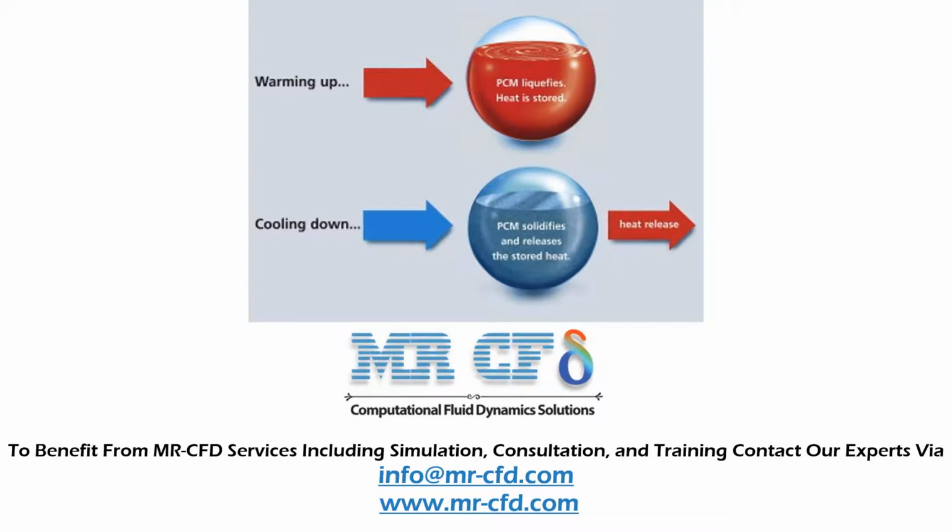Thermal energy storage in these materials is achieved during the phase change process, solid phase to liquid or vice versa, so that when the phase changes from solid to liquid, they absorb heat from the environment, and when the phase changes from liquid to solid, they return the heat to the environment.